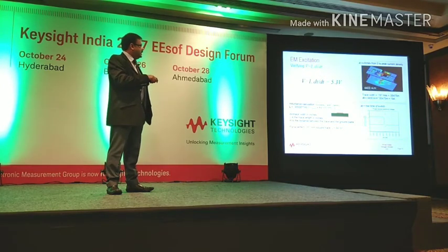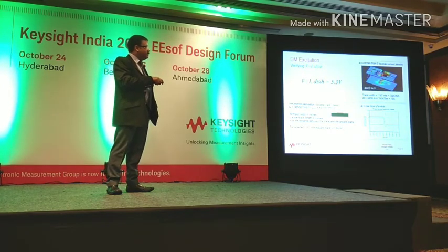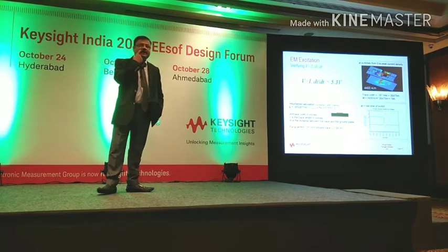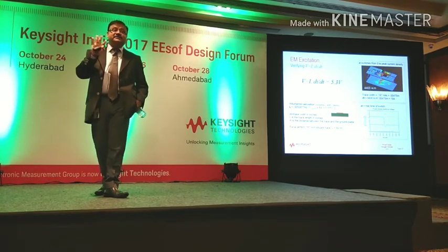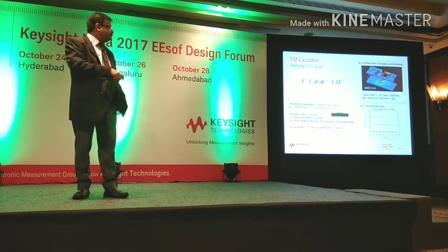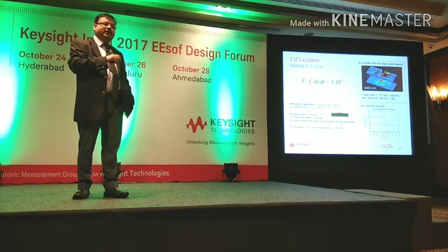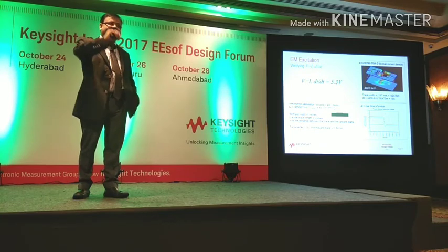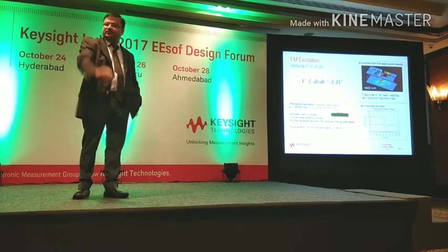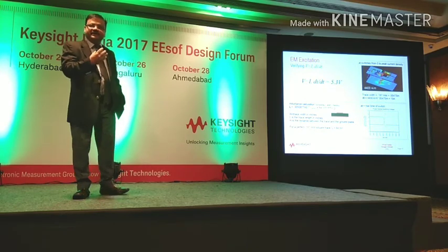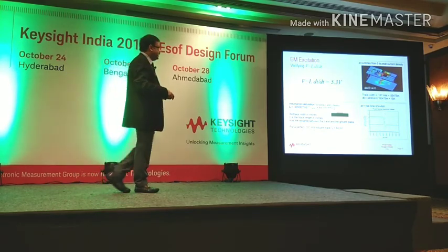Right? So now we look at what's happening. Why is that area causing this? L di/dt. Everybody understands this equation, right? So the higher the L, the higher the contribution. The longer the trace, the higher the inductance, right? So you need to shorten this loop, shorten this inductance, and this will become okay, right?